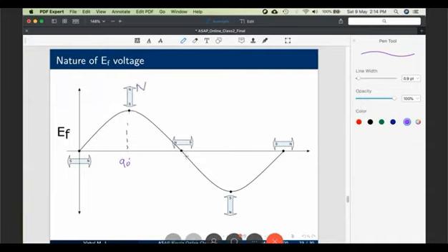Then as it rotates further, it becomes 0 again, but there is a difference. North pole is towards your left side. Here, south pole was towards your left side. It is rotating in anti-clockwise direction like that. Then at 270, it takes its minus maximum value. Again, they are not the same. The poles are vertical, but the south pole is now upward and north pole is downward. So north pole was upward, and it comes back here.